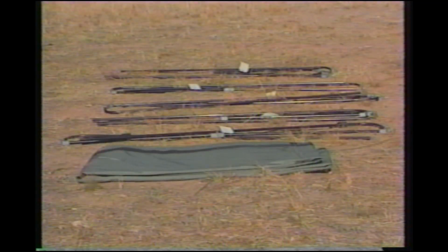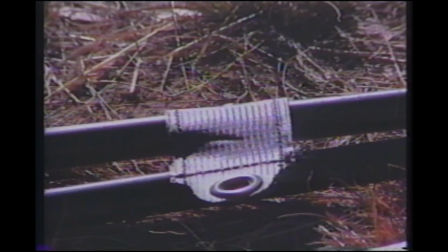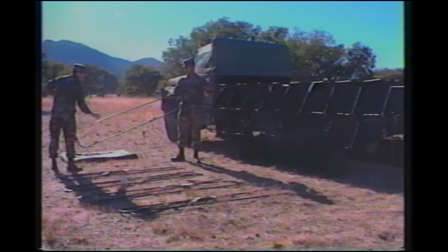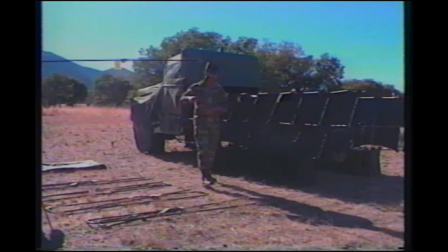The next area we will cover is the installation of the cargo compartment support bows and canvas cover. The installation of the 5 support bows will require 2 personnel for easier assembly. Installation should begin from the front, with the number 1 bow being closest to the cab and the number 5 bow placed at the rear of the cargo bed. The number 1 and number 5 support bows have tabs with grommets on top of the upper sides of the bows. The other 3 support bows may be placed in any order between the number 1 and number 5 bows.